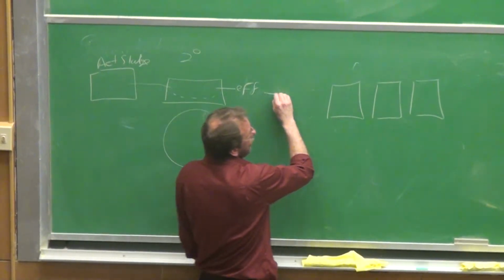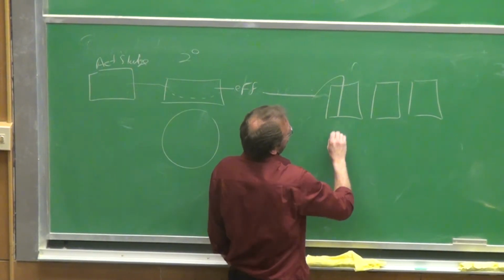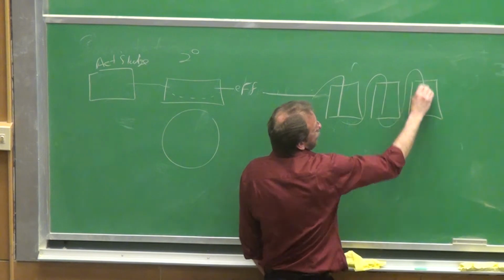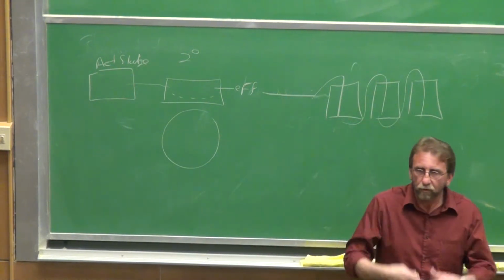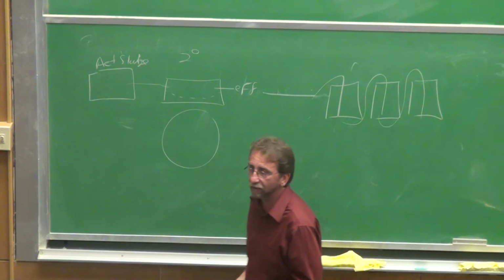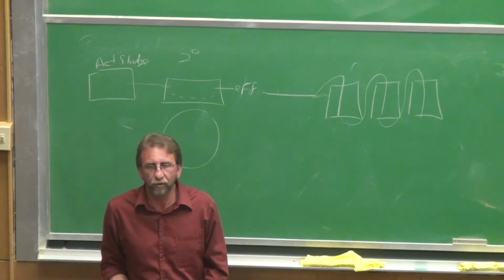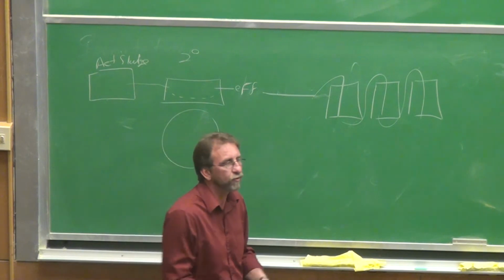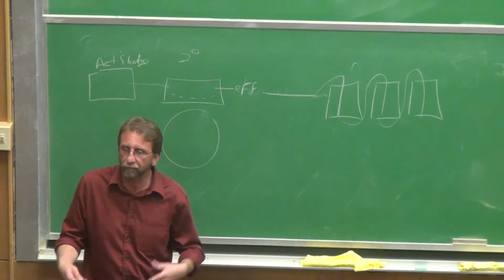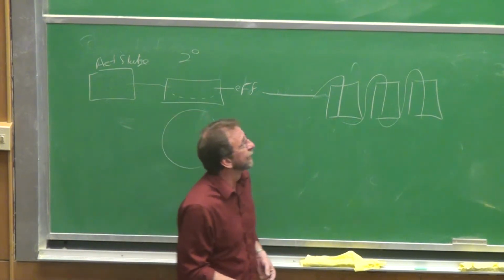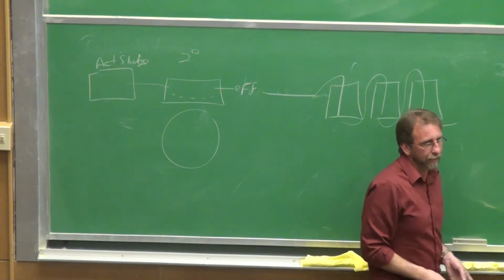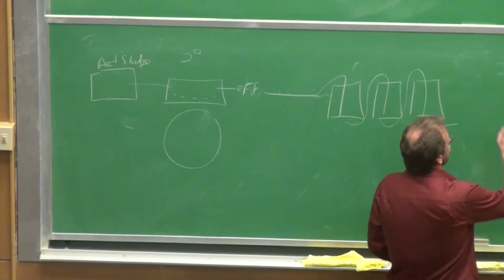We'll run the effluent down over the sand, and this is going to help remove a lot of the particulate matter. In addition to that, a lot of the bacteria will be removed as well. You can remove as much as 98% of bacteria just simply by filtering it through sand. But there'll still be some bacteria that get through.